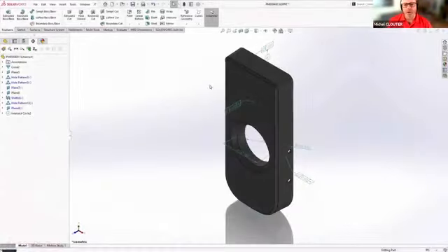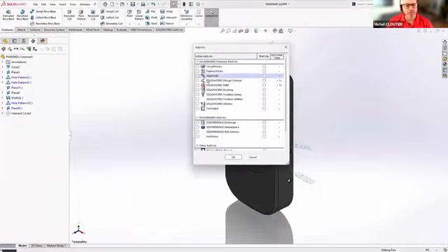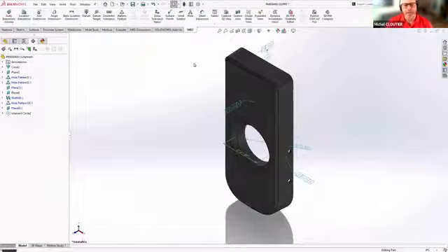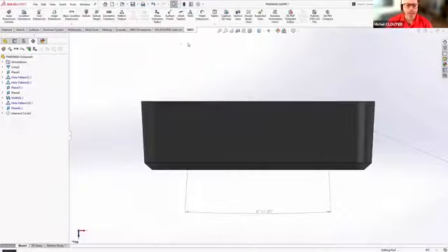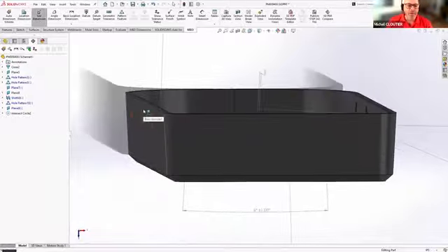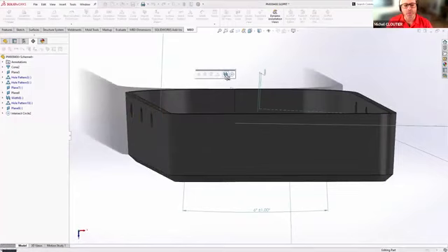So here's the part design that I want to annotate in 3D. You see that some of it is already annotated, right? There's a few dimensions on it. I'm going to turn on my SOLIDWORKS MBD add-in. As you can see, it's a proper add-in now, so it makes it much easier to float around if you're in a network environment. And here's an example where we want to dimension the angle, and that, in the past, proved to be very difficult to do.